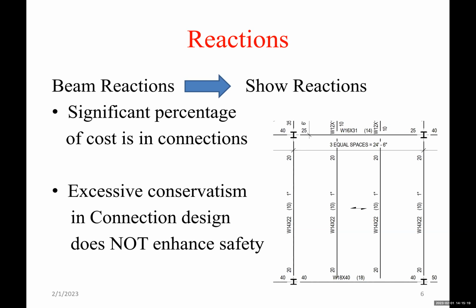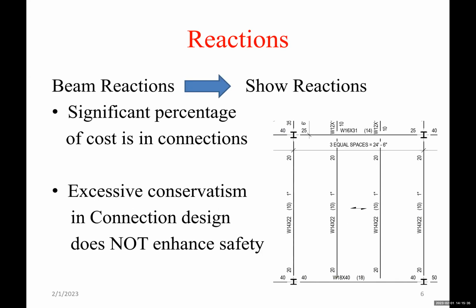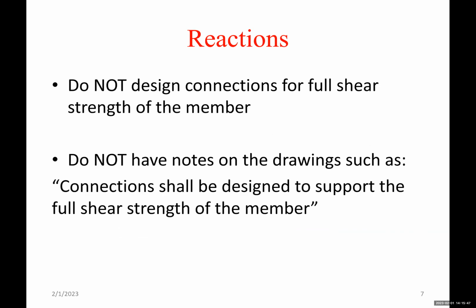Excessive conservatism in connection design does not enhance safety. Because if we have a note like this, we may have a concentrated load that we don't pay attention to. I'll show you an example, and that will lead to an unsafe design.